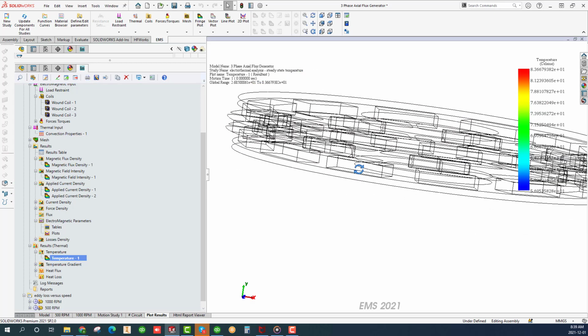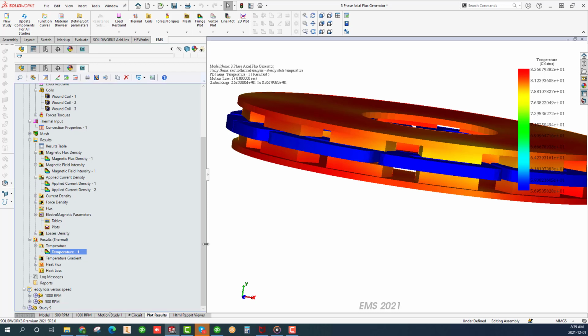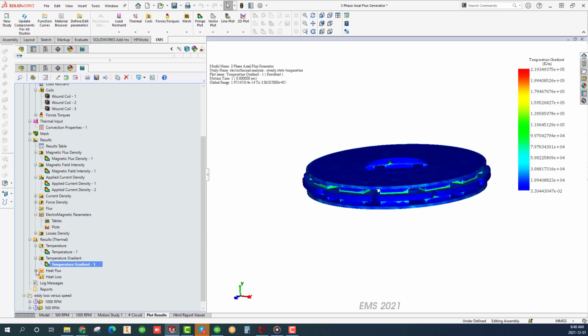The magnets themselves do not have any loss, but since they are in contact with the rotors, they heat up through the thermal conduction mechanism. Again, depending on the magnets used, such temperature may indeed demagnetize the magnets.